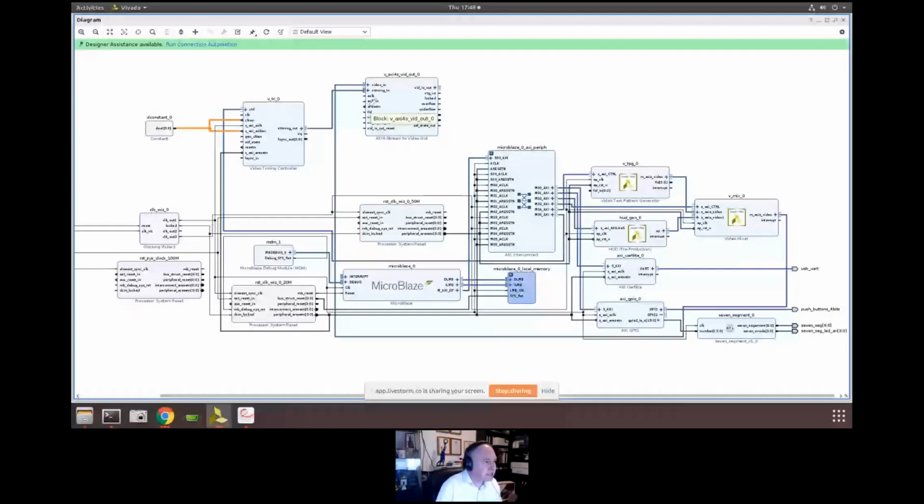And then we're going to connect the AXI stream clock here. So this aclk, we're going to connect to the video clock, because it's running at that megahertz clock. We're also going to connect the enable with the enable. We're going to connect the enable to this one here, and we're going to connect the video out clock enable to the clock enable as well.